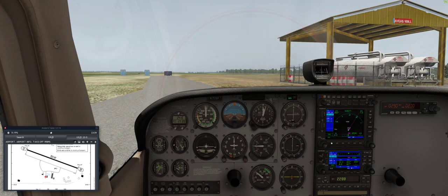This button, CDI, also up here, you have one. They both do the same thing. We want this to be in GPS mode, and notice it is. Probably because I had it that way the last time I shut down the simulator. It by default comes up in VLOC mode. That is not the mode you want if you're following a GPS waypoint plan. If you don't do that, the autopilot will seemingly go off in just whatever direction it feels like.